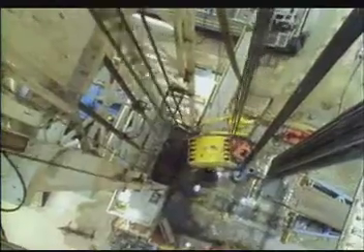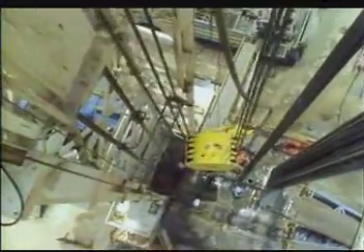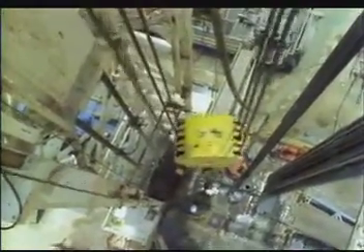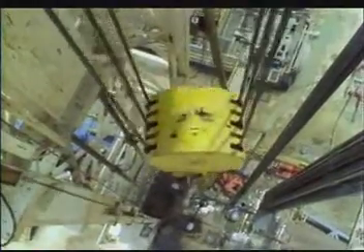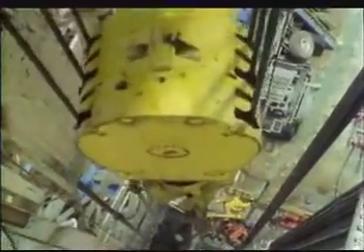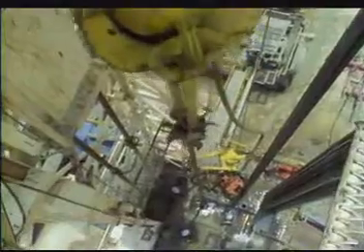And, of course, the rocks themselves can make things unpleasant. Gumbo shales which stick to the drill pipe and plug bits, salt formations which ruin costly drilling fluids, and high permeability rocks which steal the drilling fluid from the hole.